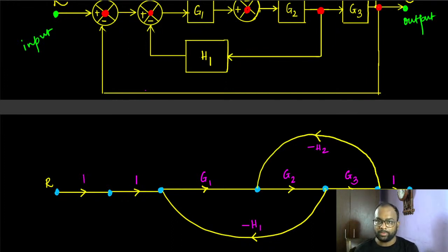It won't be just a large noise or large bang. It is additional energy proportional to whatever signal input is coming through. That's the job of an amplifier. And if the amplifier has a gain of 1, it's called a buffer. So a buffer only compensates for the additional energy required.